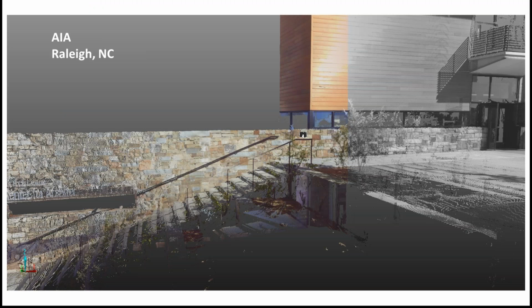And here's an example of a point cloud. So keep in mind this is not a photograph that we're looking at here. All right. So on the right third, you'll see that it's just grayscale. So that's just the point cloud data there. And on the left two-thirds, we have the colorized point cloud. So the scanner first collects all of the 3D point information, and then it takes another pass and collects all of the photography. And the software that we'll look at, so mainly FARO Scene or Autodesk ReCap, inside the software it takes all of the information of the photography and overlays the color imagery onto the point cloud.